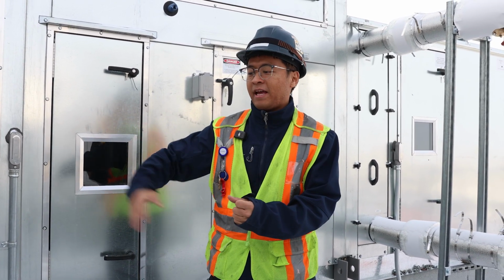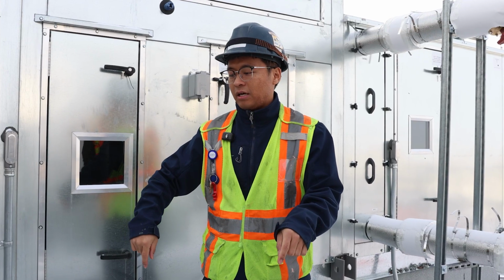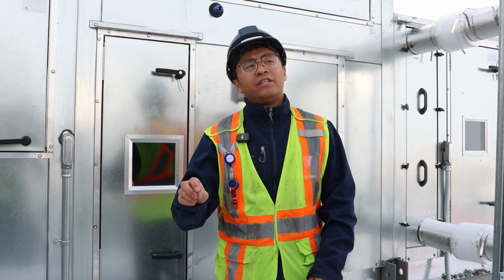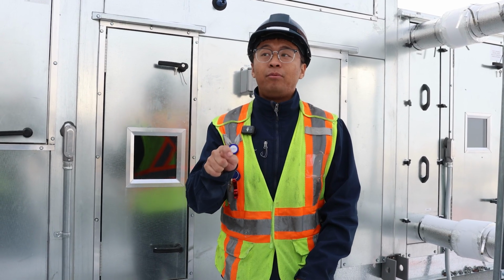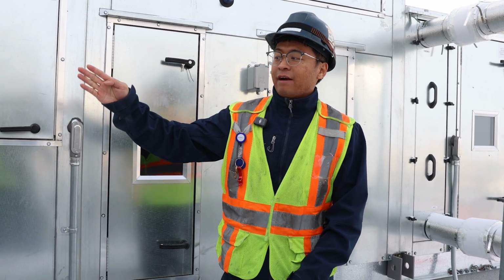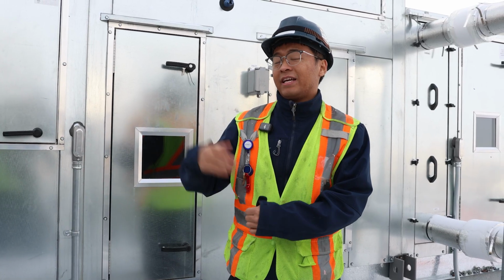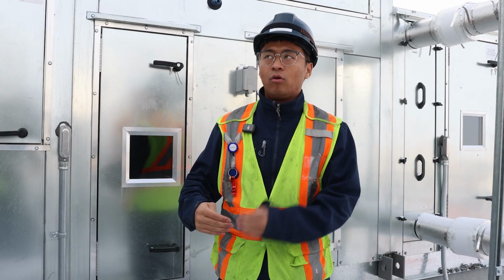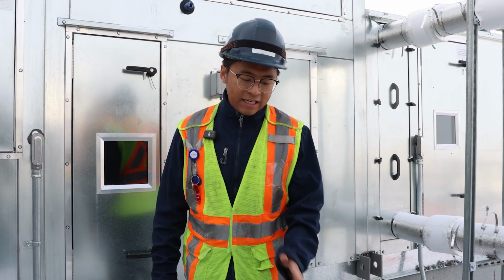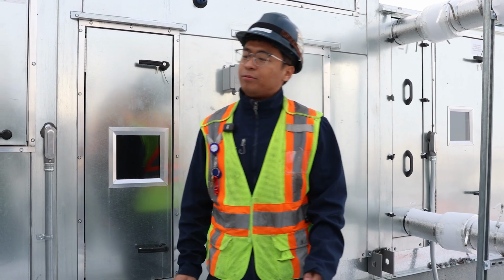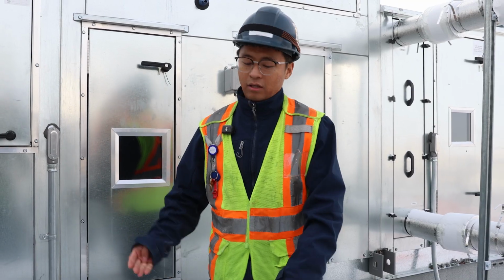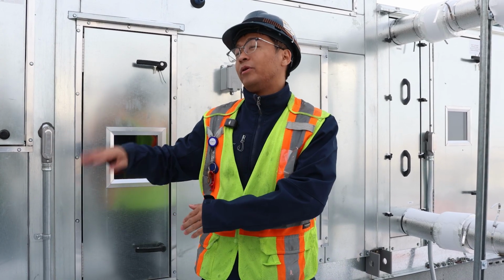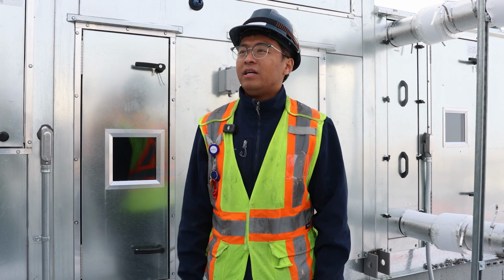So same thing, just like the makeup air unit downstairs. So it's like a heat pump loop. Exactly, yeah. It will have a cooling side isolation valve and a heating side isolation valve. Depending on the heating season or cooling season, they will be switching. Yes, this is also a part of the building loop. So right now, it's in the winter. This is our heating, and it's fed off the heating loop, the building heating loop. Yeah, same loop.